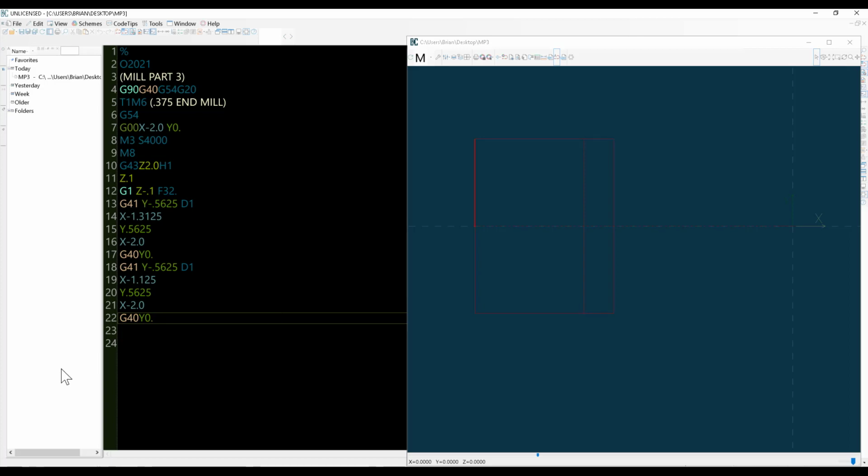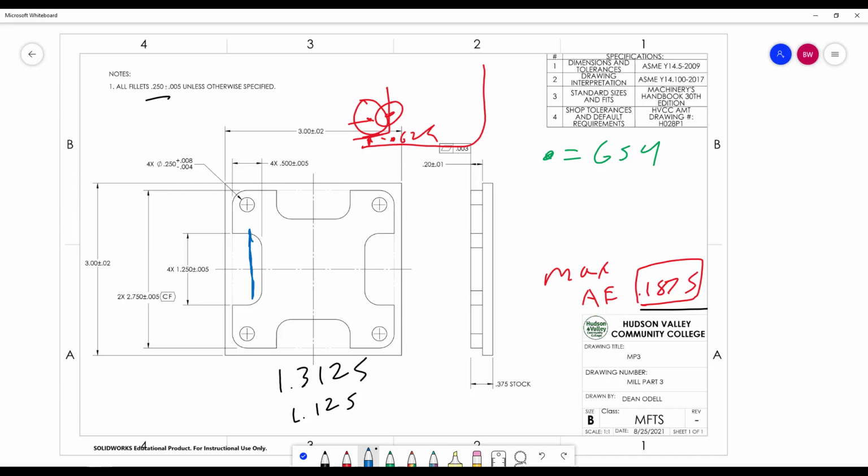We are a 1/4 inch away, so we could take that in one shot. We did rough enough out. That's fine. The cutter's 3/8 would be taken over a 3/16 width of cut, which is sort of an issue. It would probably be fine, but let's take a look and see if we can take a little more material. The problem is that we need to avoid these radii.